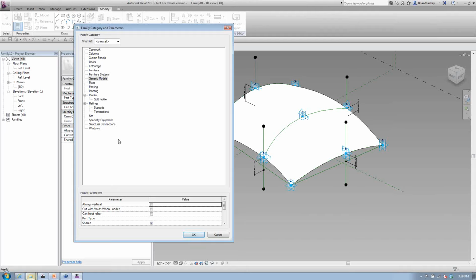So I'm also debating with the repeater command and some of the features we can have, possibly nesting in casework. So I could just go draw casework and say, give me 10 cabinets, and it'll scale the casework accordingly. But again, there are a lot of different tools and ways you can get it to work. I had somebody create an adaptive component because around every window, it was existing windows and they were all different sizes. They wanted to be able to just snap to the windows and put the lintel and the sill in an existing building, so we did it that way. They also had some where the arcs were different at the top, so we created an adaptive component with an arc top. A lot of different ways to get this to start working.